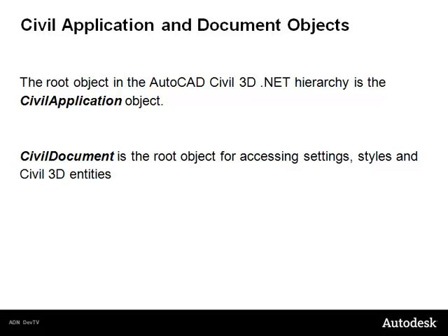Therefore, if you need to access application level methods and properties, such as the collection of all open documents, information about the main window, etc., you need to access them through the AutoCAD application object. You can get more details about this class in the ObjectARX managed class reference document.